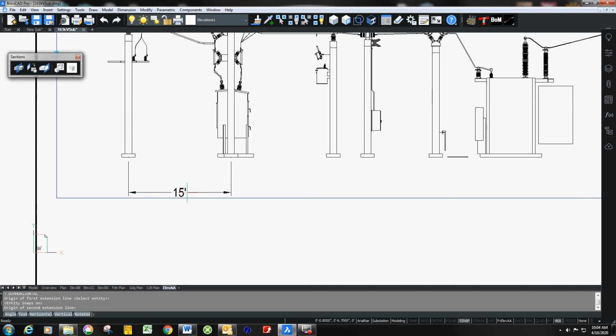You've got to be a little careful. If I don't turn the snap off here, this thing will find a snap somewhere, and it won't be where I put it. Now once I've done that, turn snap back on. Now I have to tell it dim continue, and so I can come over here and just hit these snap points, hit close to them.